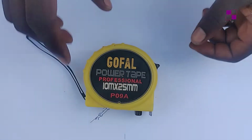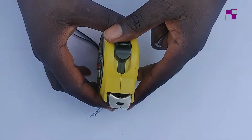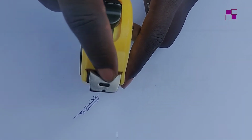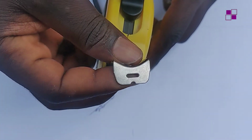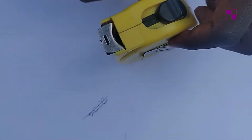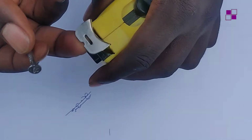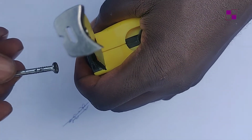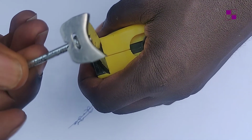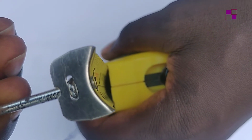All right, so you will notice this. I know plenty of us have not noticed it actually. Most of the tapes have this O at the initial part of it. The function of this O is to support you when you are measuring around a nail. Let me say, for instance, I'm measuring around this nail. You put it like this, and the nail fits directly into it.